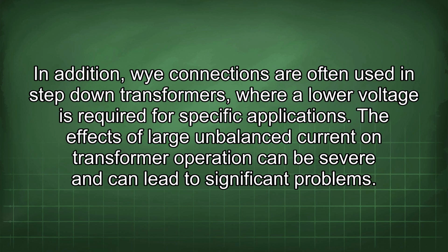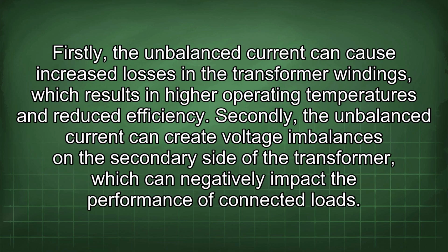The effects of large unbalanced current on transformer operation can be severe and can lead to significant problems. Firstly, the unbalanced current can cause increased losses in the transformer windings, which results in higher operating temperatures and reduced efficiency. Secondly, the unbalanced current can create voltage imbalances on the secondary side of the transformer, which can negatively impact the performance of connected loads.